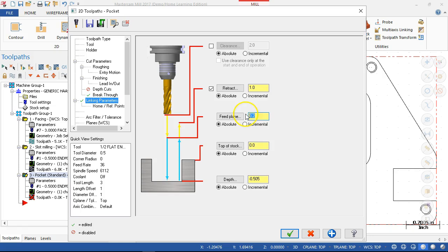Now we'll go ahead and do 1, and this is all interior to the part, but I mentioned clamps. As soon as you engage clamps, that retract plane becomes a lot more important. Feeding between the same geometries on the same operation becomes much more important.